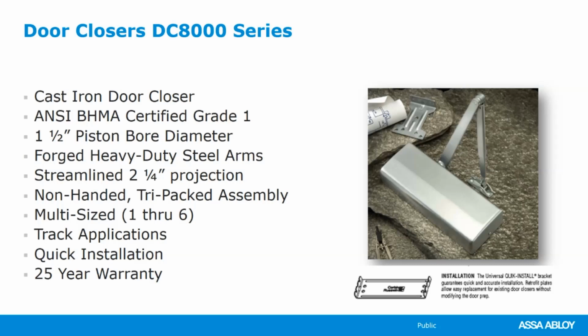And looking at this closer, this is the one that we would put into a specification. It has what we call a full-featured closer, which has sweep, latch, and back check. We can do any one of the mounts with it: regular, top jam, parallel, or track.